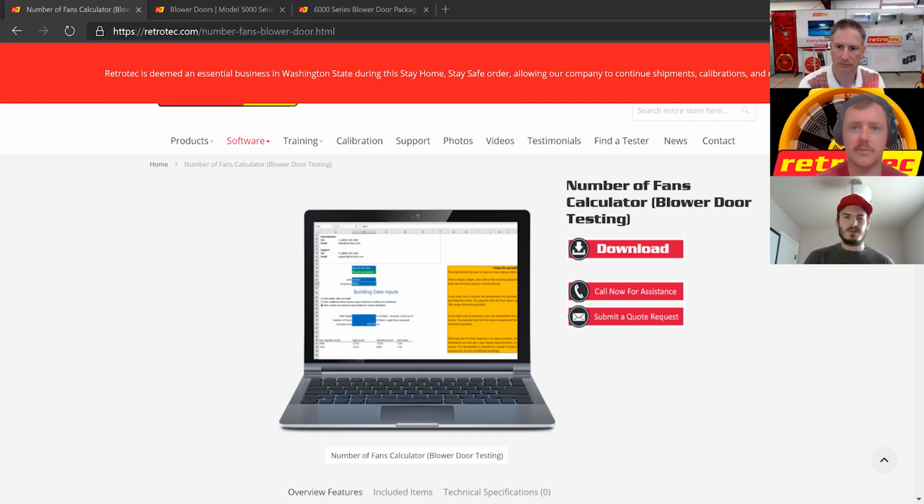You just compare that to your cutoff. As an example, 3,000 square feet, 14-foot height, 5 air changes gives you 210,000 cubic feet per hour. Then that 210,000 cubic feet per hour is divided by 60 to get your CFM. In this case, we could definitely test this house with either fan. So it's a quick rundown, but this is really handy to know. And you can do the same for other kinds of testing, like duct testing. As long as you know what your cutoff is and what the max flow of the fan is, you can determine how much flow you'll need.